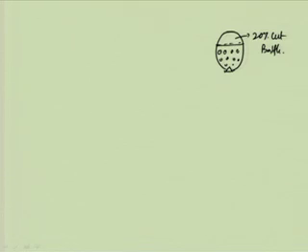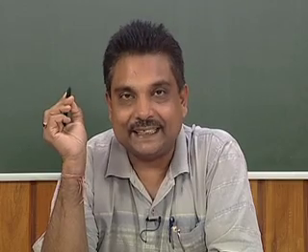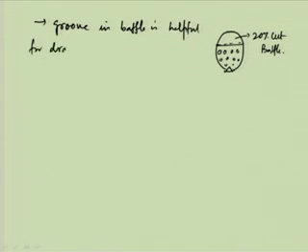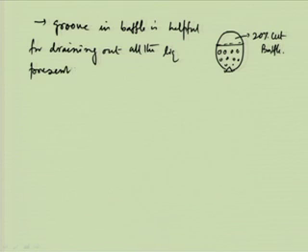What this groove is for is that when we need routine maintenance, the groove in the baffle is helpful for draining out all the liquid present in the shell side, because this draining out is needed during maintenance.